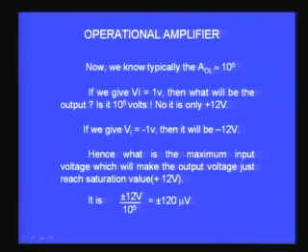Similarly, for the negative side, you would find there is a limit to the output voltage corresponding to plus or minus 12 volts, or plus or minus VCC as we call it. So, that shows what will be the limit of the input voltage. The limit at the input voltage should be plus or minus 12 volts, which is the limit for the output voltage, divided by the gain gives me the input voltage.